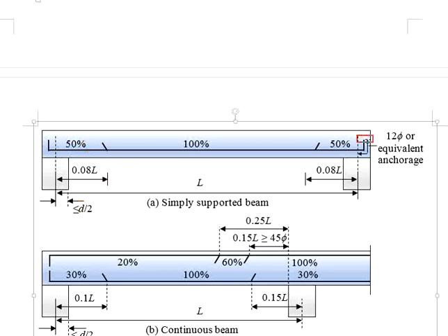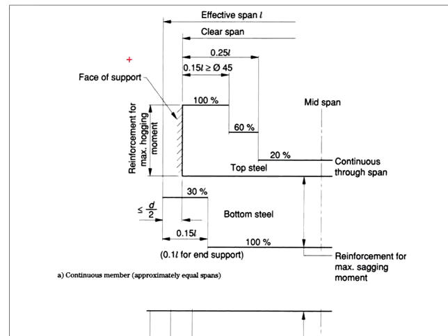And then you need a full anchorage length, which is at least equivalent to 12 times the bar diameter.